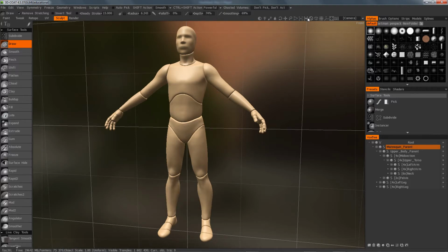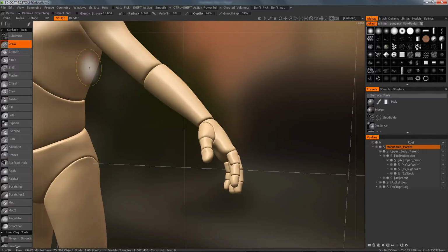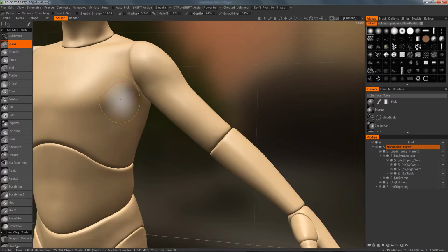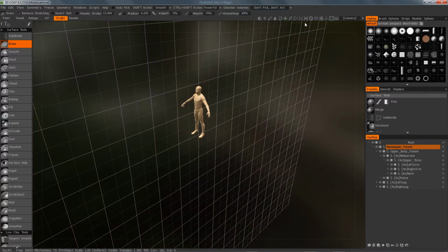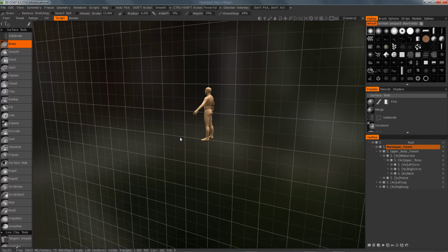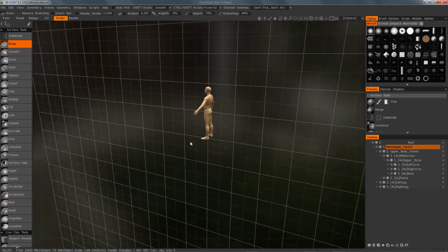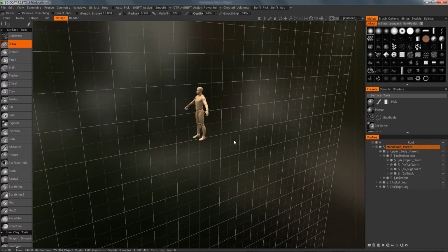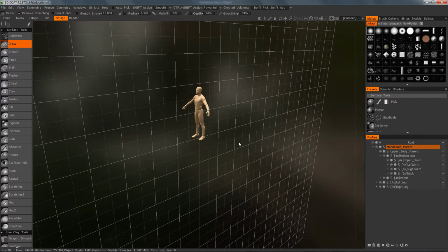This focuses on your pen. This is nice because wherever you place your pen, wherever you're drawing at, you can zoom to that place, and it will focus on that. That can be useful. Okay, this puts the camera back to its default. This toggles between perspective and orthographic view. Okay, just like in Rhino, where we have, in Rhino they call it parallel and perspective.